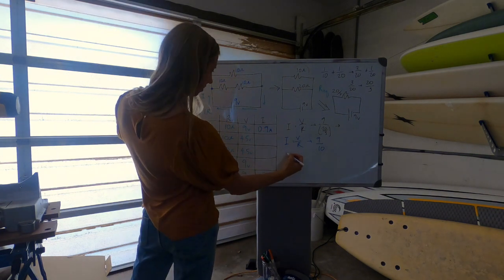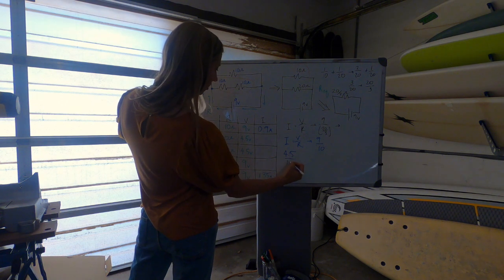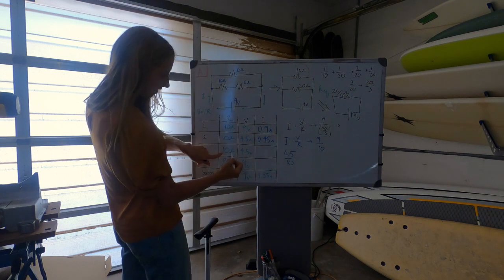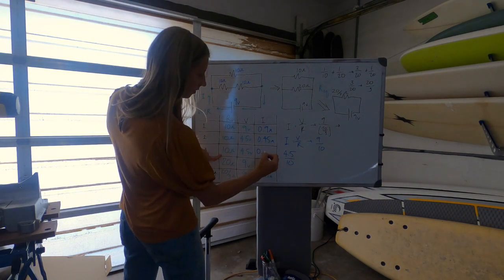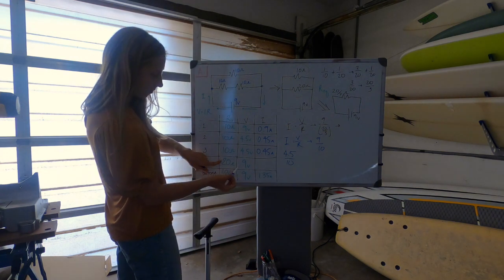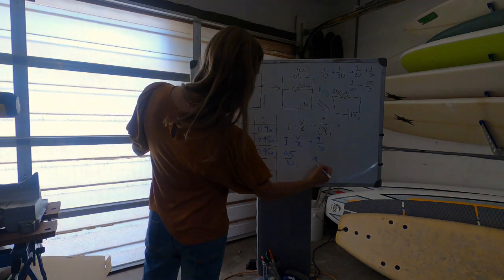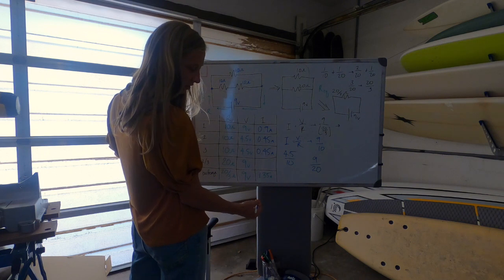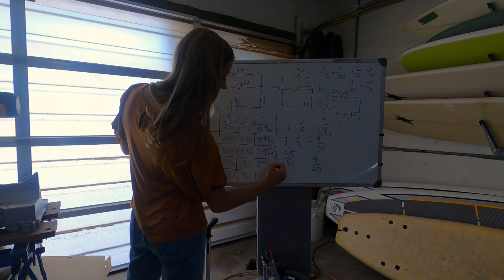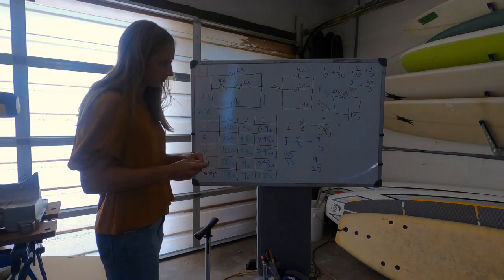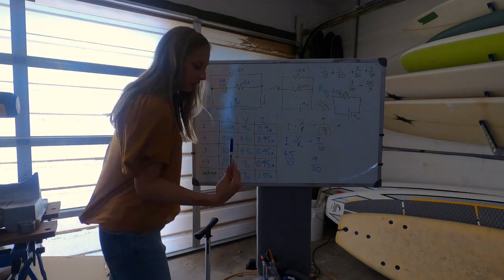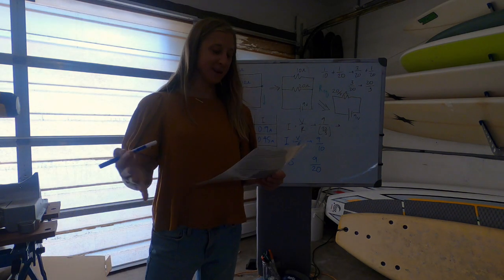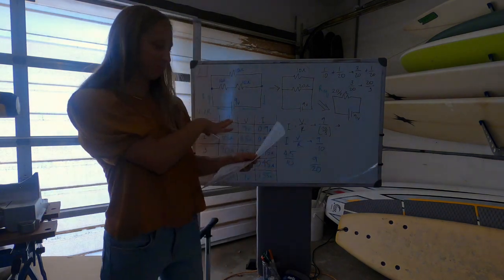And what about this one? We're doing 4.5 over 10. So that should be exactly half of that. So 0.45 amps. This is the same thing, 4.5 over 10. And then this we'd be doing 9 over 20, which reduces to the same thing. So that would also be 0.45 amps. Okay, so there's the math to complete the chart. And now we have some questions that we need to consider. So the first question says, on a separate sheet of paper, draw a schematic version. We already did that, and simplify it to solve.